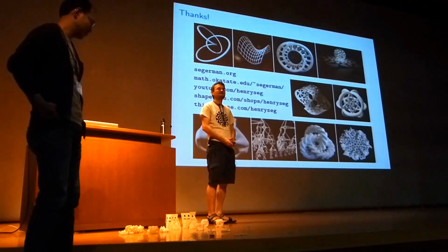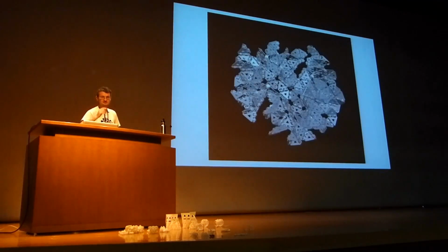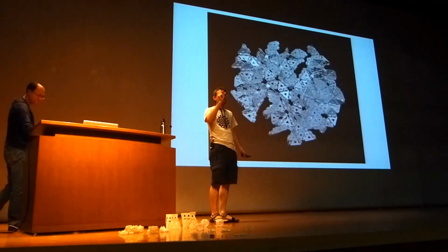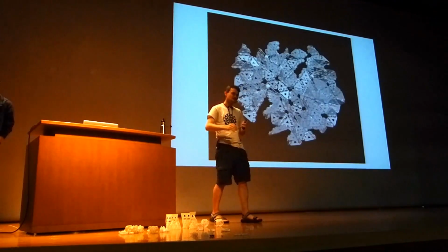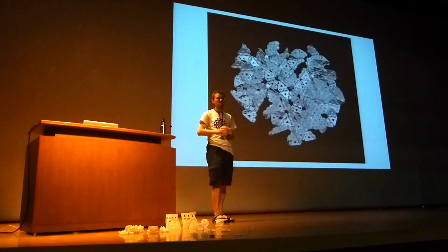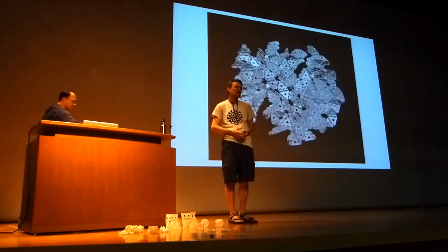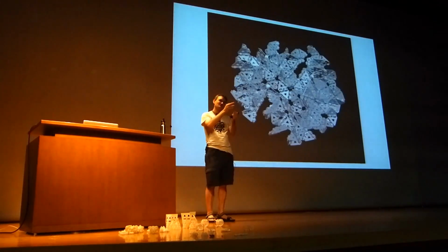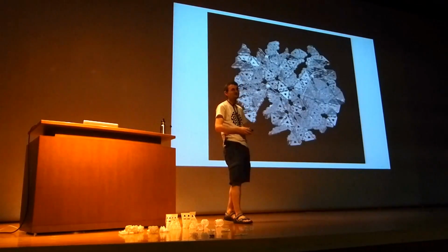How difficult is it to get the 3D printer to lock one triangle around the next triangle without having the plastic glue together? Right. Shapeways, the company that I use, recommends a tolerance of 0.5 millimeters between two pieces that are not supposed to be glued to each other. So you just make hinges where they have that much gap, and then it works. Somebody at some point hoovered out all of the unused material from inside of all of those hinges, but it wasn't me, so I don't know how difficult that part was.